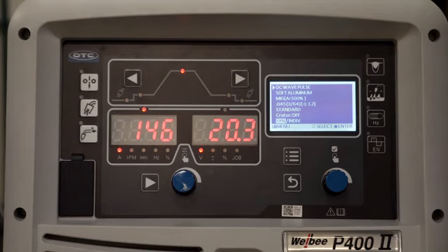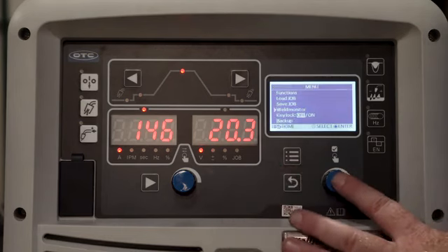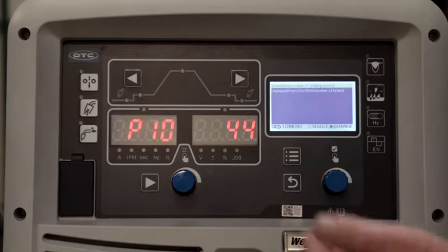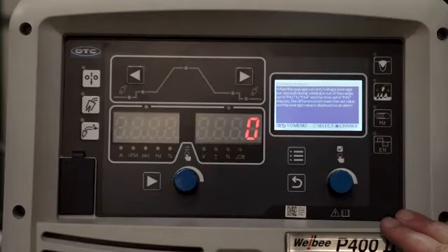The weld monitor data is also available from the menu button on the front panel. Simply push the menu button, scroll down to Weld Monitor, press Enter, and it'll tell you information like how many welds have been made, how many pounds of welding wire have been utilized, and the total number of arc hours that have been used. It also has the ability to set alarms and errors to monitor the welding current, and when welding current varies by more than a specified amount, it will either send an alarm to the operator or stop welding.